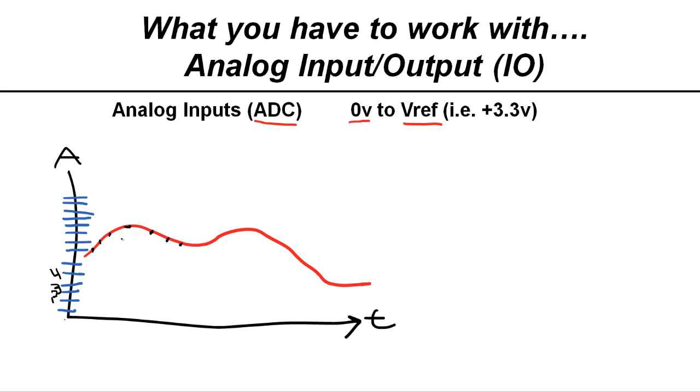Then all you have to do is convert that number, once you know the reference voltage, back into what it is. Now, oftentimes the microcontroller has a somewhat small range of what it measures. It's almost always 0 to some reference voltage. If you want higher or lower voltages, you have to design an external circuit to map that external voltage into the signal range of the ADC. But that'll be a topic for another video.